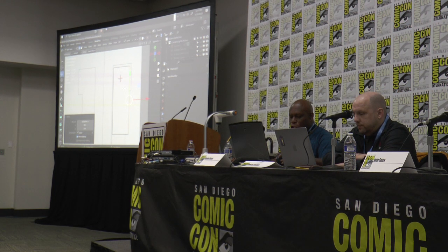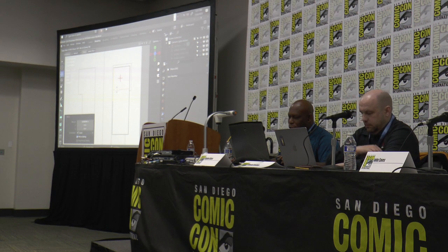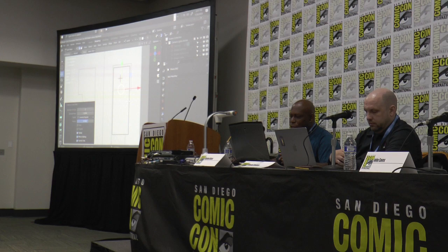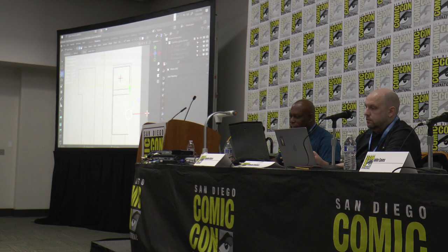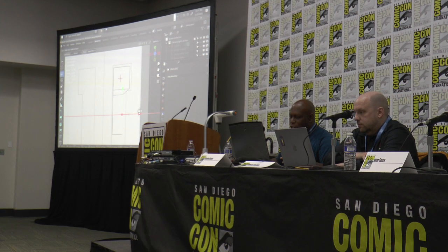So, Control R, slice, put it right about there, okay? And I think I might do another. So Control R and one more slice. And then I'm going to grab this edge and I'm going to do something like that. And then I think I'll bring this edge on down. I'm just playing right now.